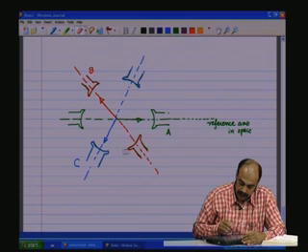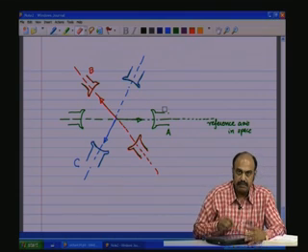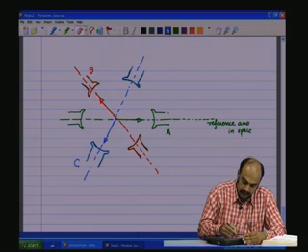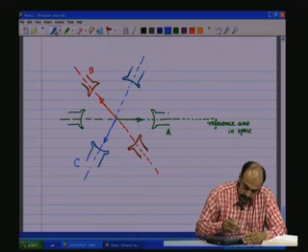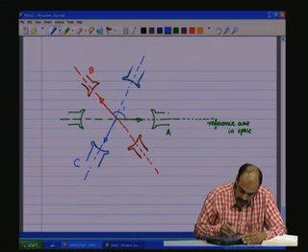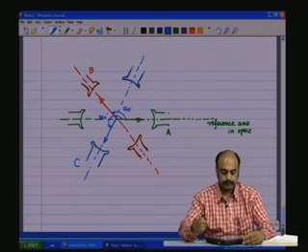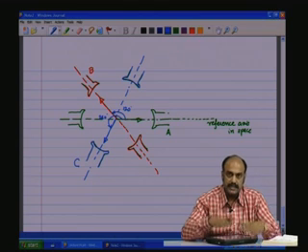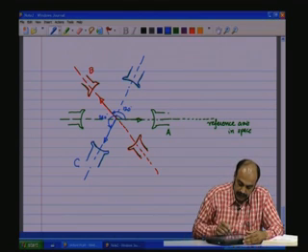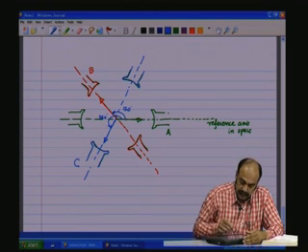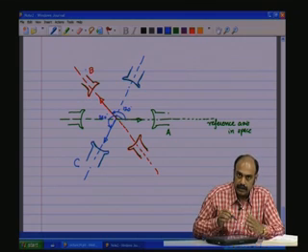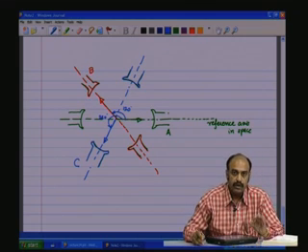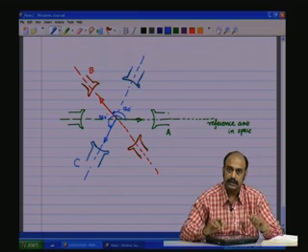Now, by fixing these poles in space, and now these are 120 degrees with respect to each other, this is 120 degrees and this is 240 degrees. They are fixed firmly, and the flux densities in each of these axes are going to swing only in those axes, and they can be modulated only along those axes by controlling the currents through that axis.